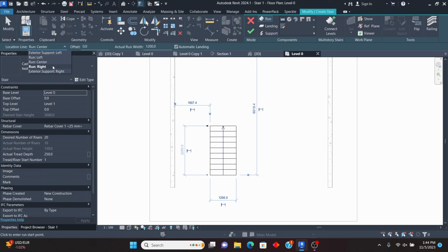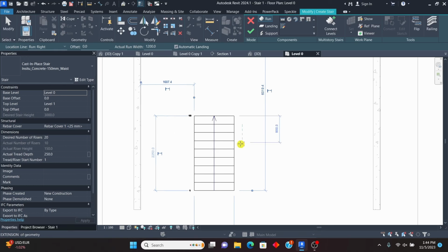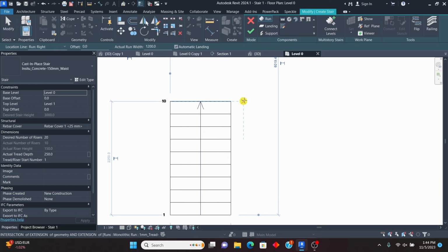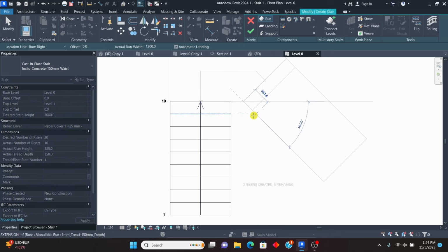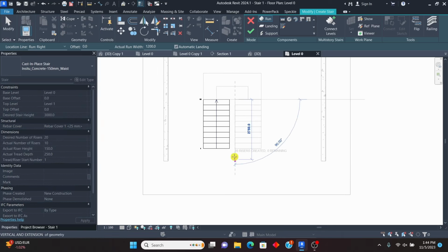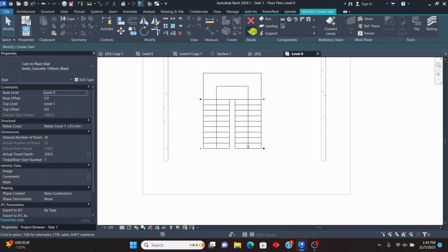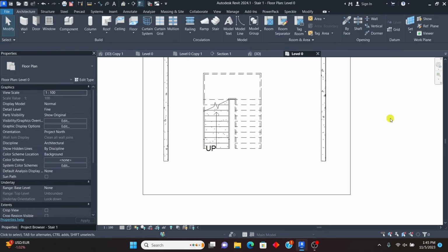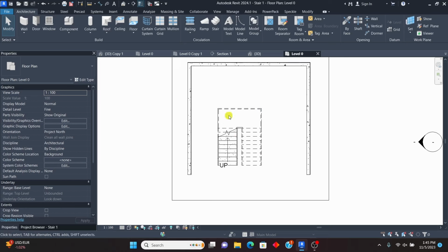This is just the alignment as you create your stair to the right. And maybe from this point, I just want up to somewhere here, and click that point. You can counter check the actual spacing between the stairs there. Now I'll drag all the way up to the end, and you can see we have the automatic landing there, and just click there. You can see that we have that stair, and click on finish, and just click on outside. See that we have that stair.